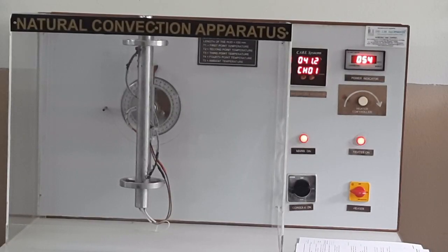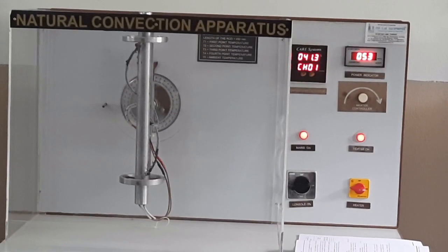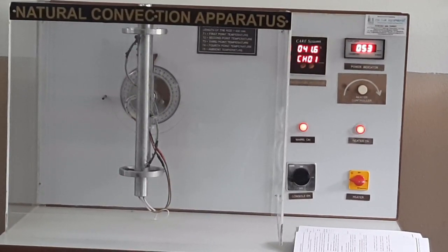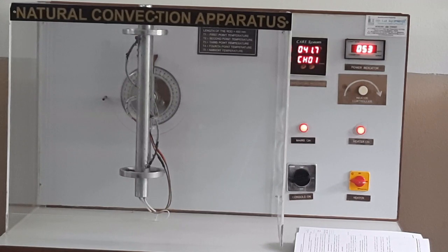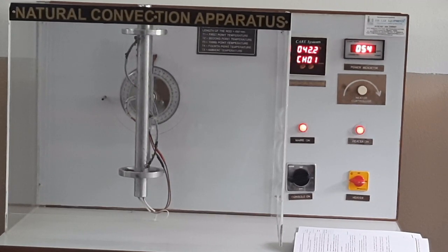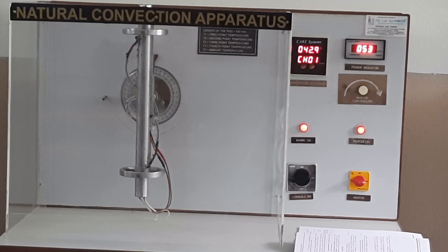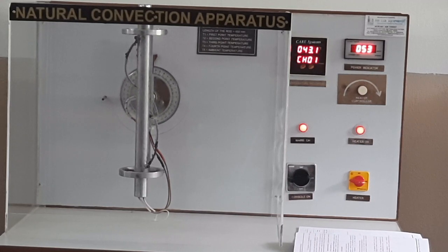The main precaution at the time of starting the experiment is that the experiment should be carried out in the absence of wind flow through windows, as well as in the absence of a fan. The second precaution, when keeping the rod in horizontal position, is that for better results the experiment should be conducted after the tube has cooled down, almost to room temperature.